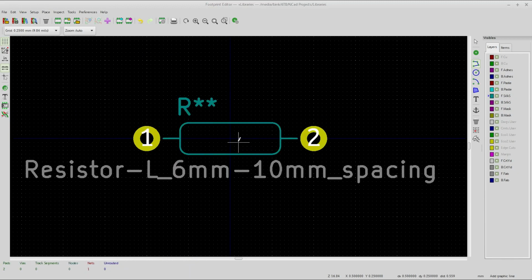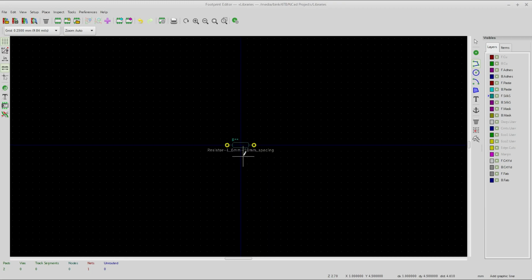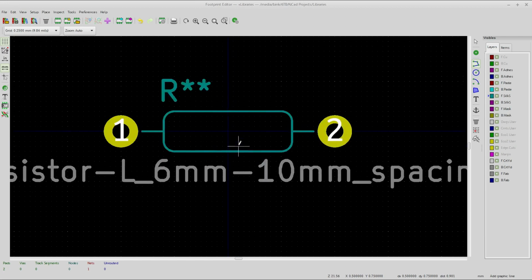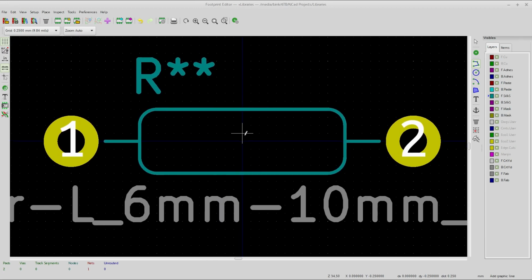When you're done, you take a look at it, see that you like it. If it's anything like a diode or an IC or anything that has some kind of indication on which direction this is supposed to go, put a little mark on it. Put a dot, put an arrow, put something on here. Remember, though, that this is pretty small. And so you do have a limitation on what size your board house can print, the font size or the line size. I found that they do a really good job. So you probably don't make things microscopic, but you can put some small lettering on here and they'll manage that, right? But what can you see, right? So there's that issue as well.